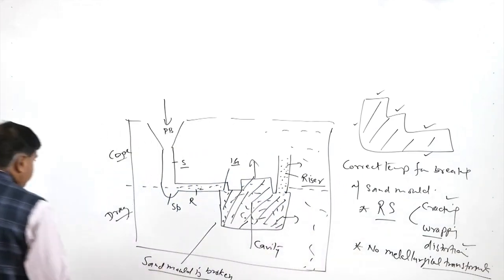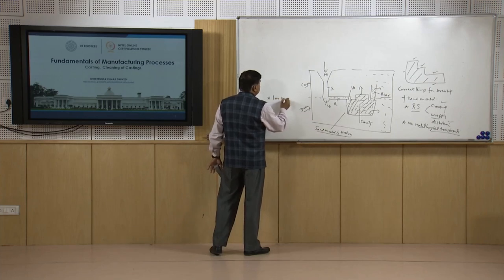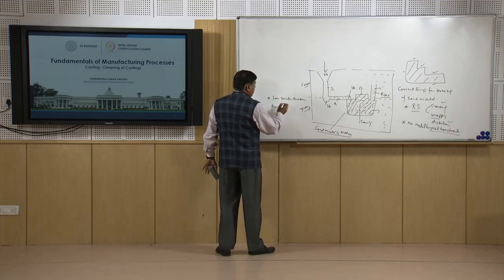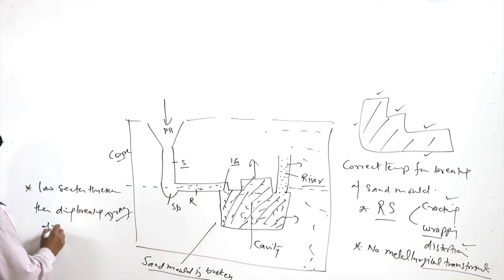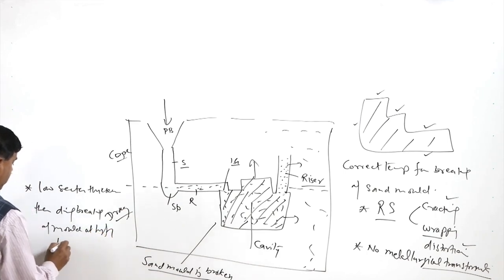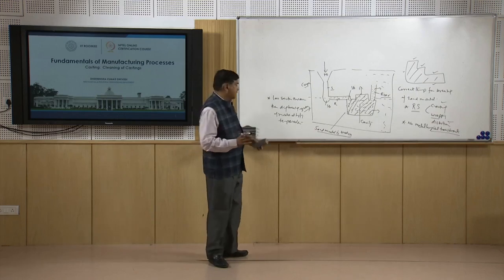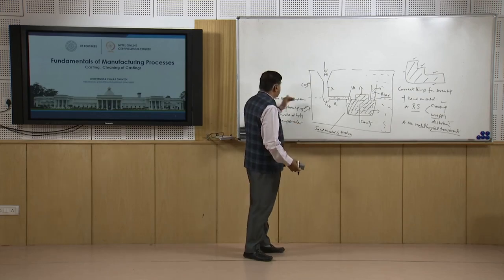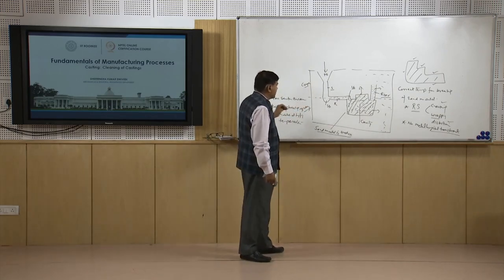Further, if the casting is of very low section thickness, then breaking of the mold at high temperature can lead to the fracture of some of the sections, because at a high temperature of the casting, if the mold is broken, then the thin sections of the casting may not be able to support the forces acting onto the casting during the breaking.